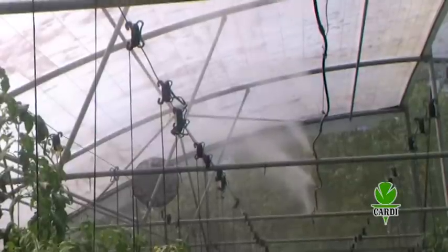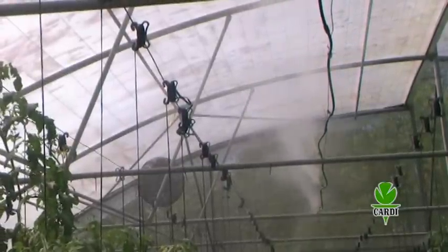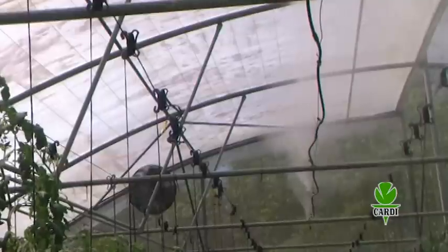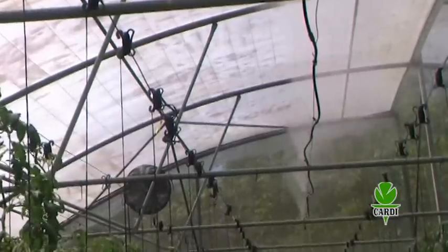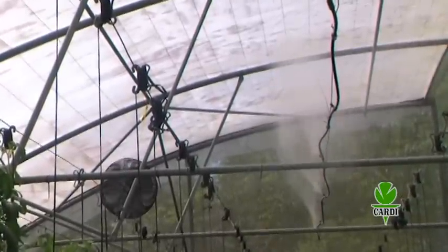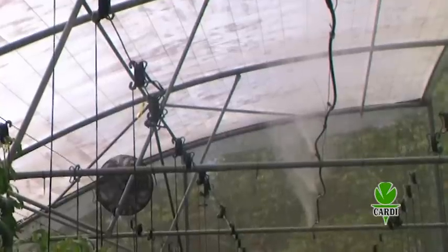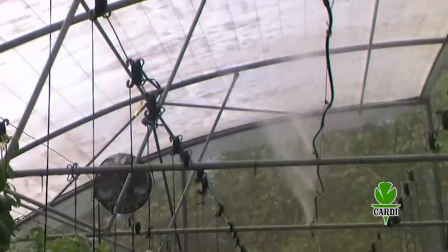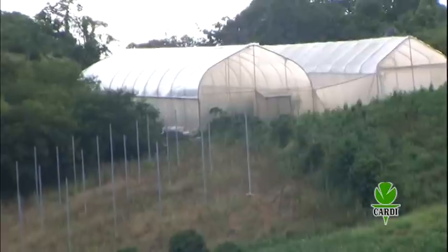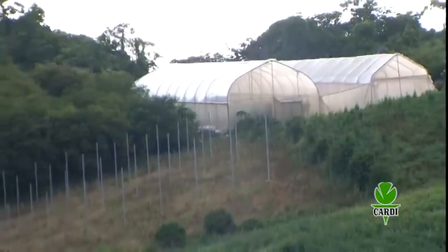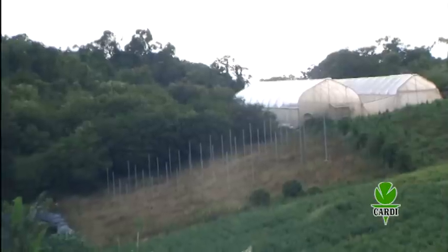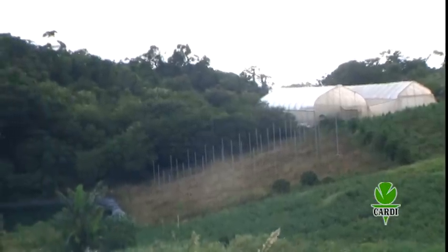High humidity environments greater than 80% do not facilitate evaporative cooling as a feasible option. The use of evaporative systems, wet pad cooling and misting, is most beneficial and efficient only in the short dry periods of the year where the relative humidity is below 50%. The cost and/or benefit should be carefully considered and would depend on climatic conditions of the area.